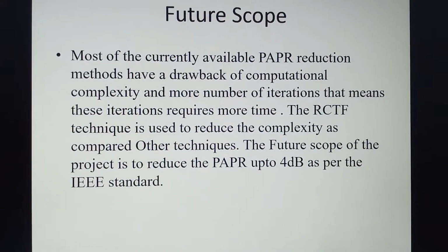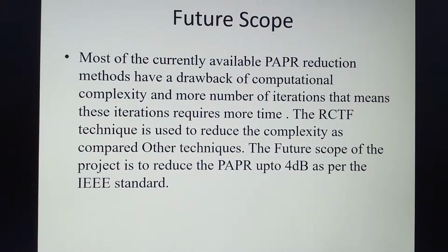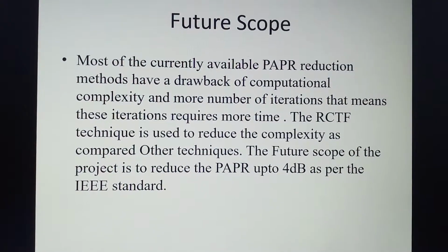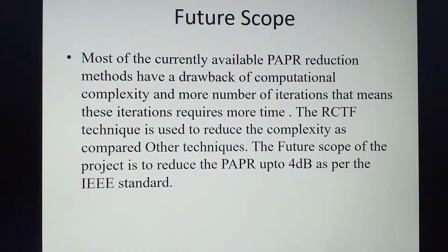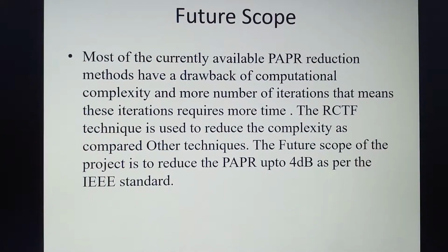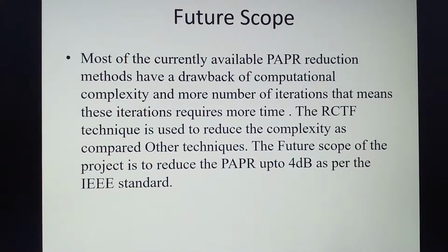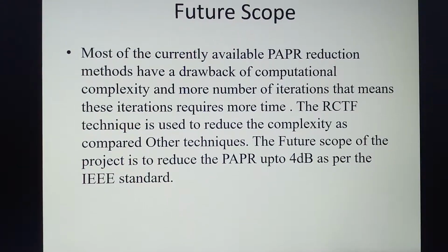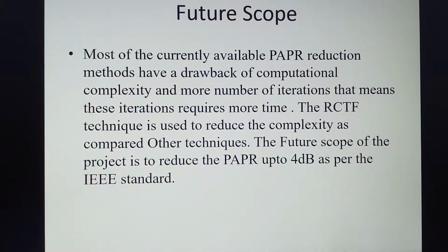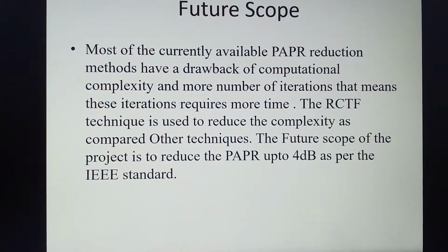Future scope of the project. Most currently available PAPR reduction techniques have high computational complexity and the techniques take more iterations. So by using the iterations, the output of the project is taking more time. So we reduce the time and also reduce the complexity by using the RCTF technique. The future scope of the project is to reduce the PAPR up to 4 dB as per the IEEE 802.11n standard.